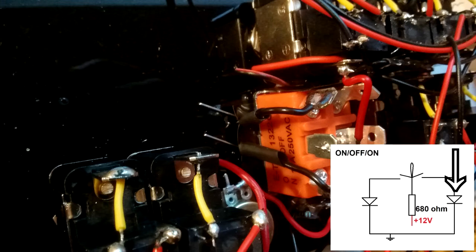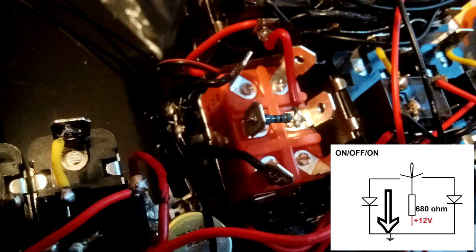At this time I made a mistake. I inverted the two black wires, so when the button was up, the bottom LED was illuminated, and conversely. In a further picture I've put the wires in the right way. The LED cathodes must be connected to the minus pole, so I've taken ground and I've soldered the two cathodes.